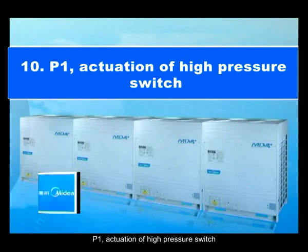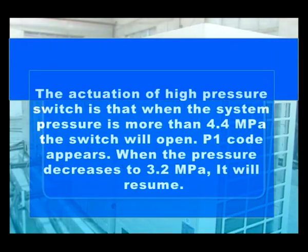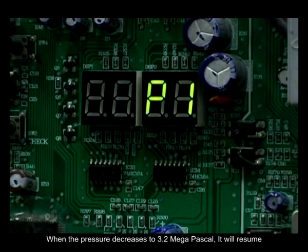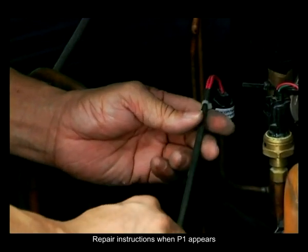P1. Actuation of high pressure switch. The actuation of high-pressure switch is that when the system pressure is more than 4.4 megapascal, the switch will open. P1 code appears. When the pressure decreases to 3.2 megapascal, it will resume. Repair instructions when P1 appears.